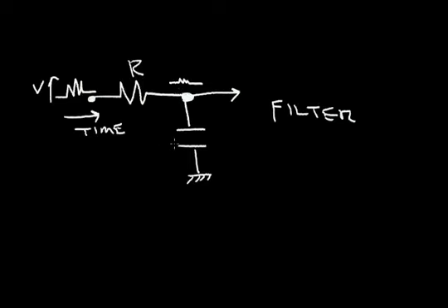We could also use this filter to eliminate very high frequencies at the input. If we had a very high frequency waveform, this capacitor will look almost like a short circuit, and the frequency here will be greatly reduced at a very high frequency. Now let's examine